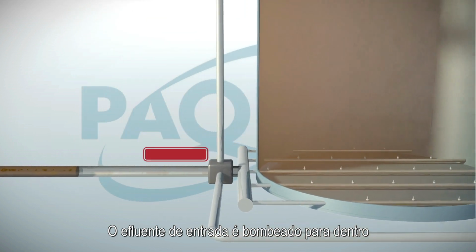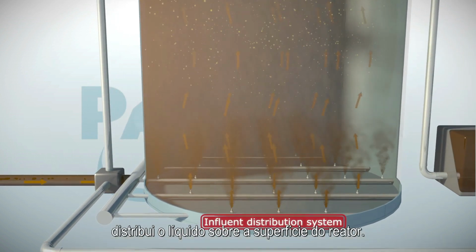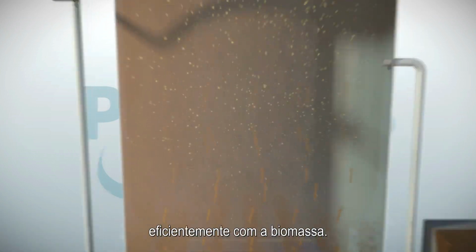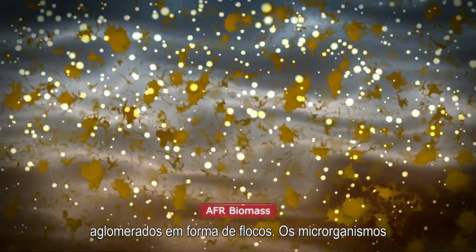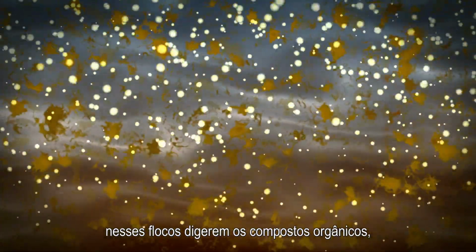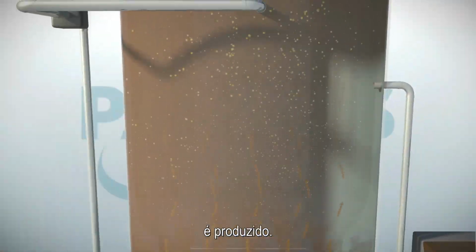The incoming wastewater is pumped into the bioreactor through the influent distribution system that evenly distributes the liquid over the surface. The liquid flows upwards and is mixed well with the biomass in the system. The anaerobic biomass forms agglomerates, small flocks. The microorganisms in these flocks digest the organic compounds, such as fats, proteins, and carbohydrates. By various microbiological steps, biogas is produced.